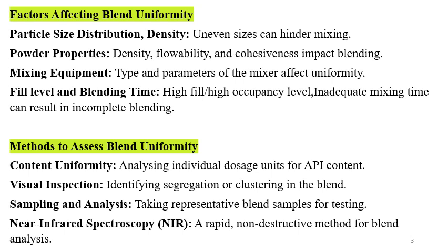Mixing equipment, type, and parameters of the mixer affect the uniformity. Blender design, blender fill volume has the impact. Fill level and blending time. High fill or high occupancy level, inadequate mixing time can result in incomplete blending. Over blending can lead to demixing and affect the BU.